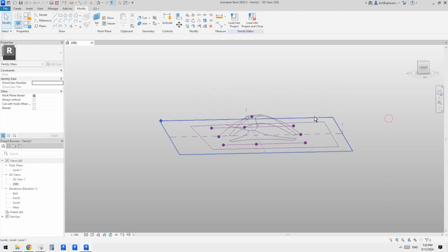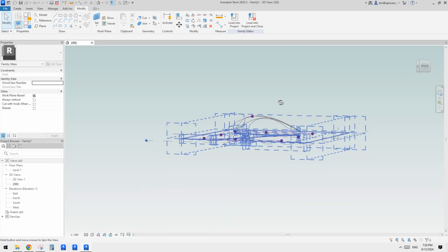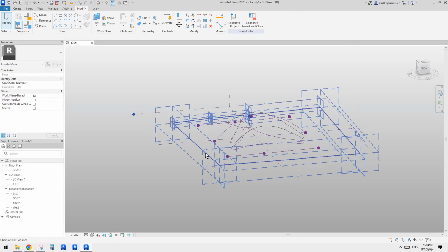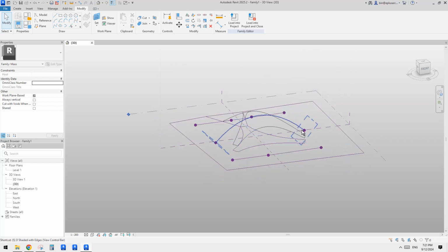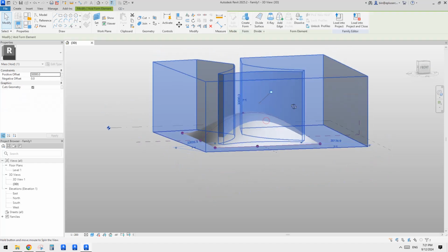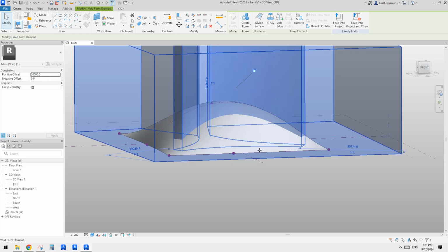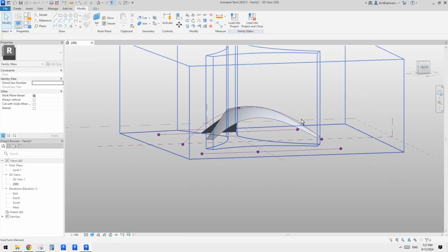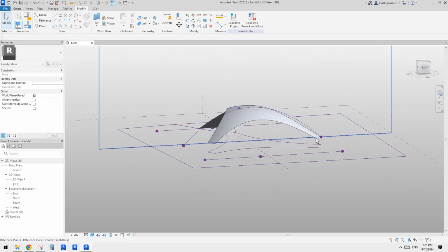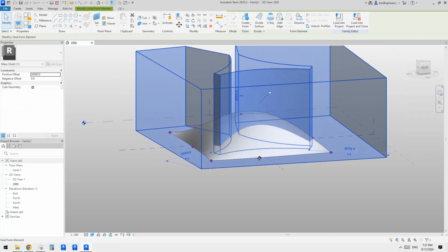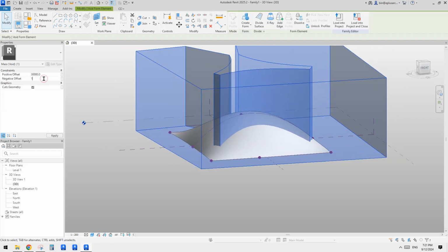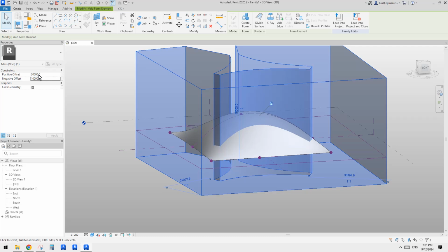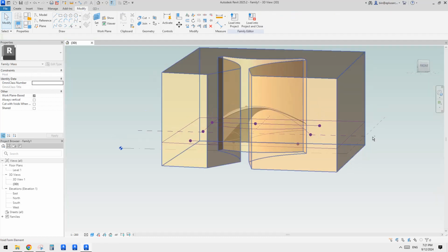Okay, and then just to make sure, because we know that this solid bit, I'll change to SD so you can see the solid bit starts from the floor, but to make sure it 100% cuts this solid, let's just add some offset to the negative, okay, negative offset.